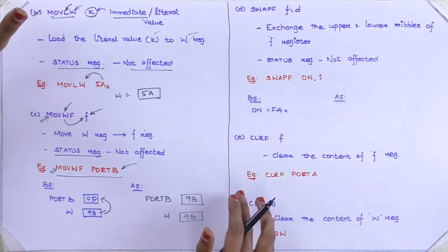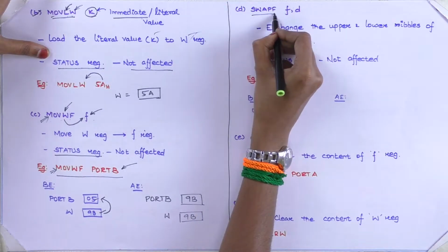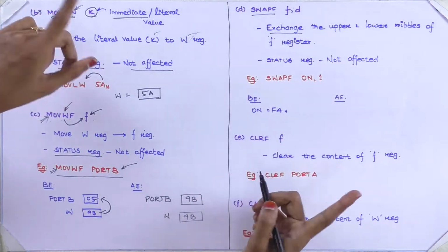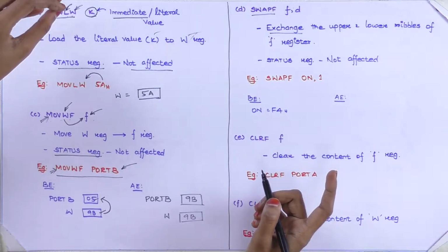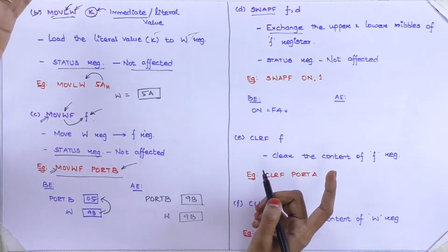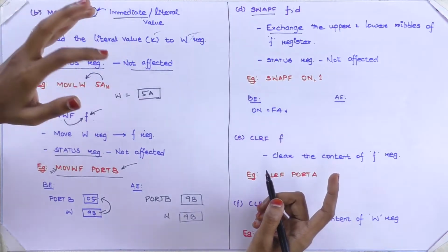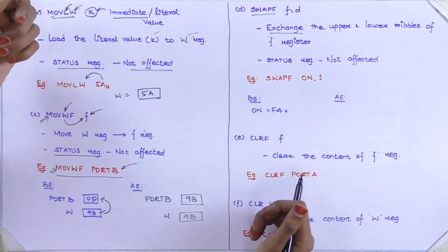The next instruction that we are going to see is the swap instruction. Swap is nothing but exchange. So the exchange operation is called swap. In 85 we have an exchange instruction that exchanges only between HL and DE. Later in 86 we have an exchange instruction that is used to exchange values between any of the registers mentioned in the instruction.